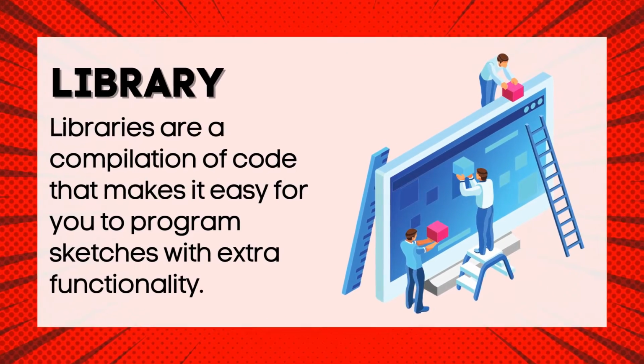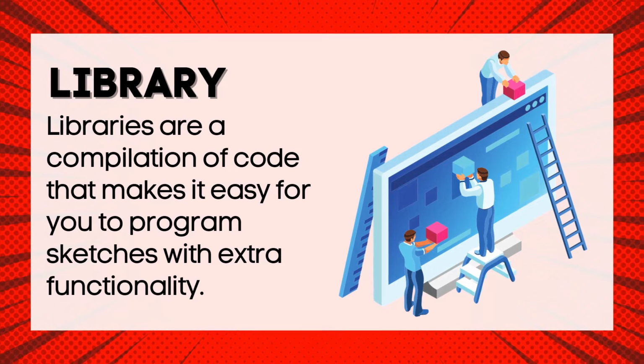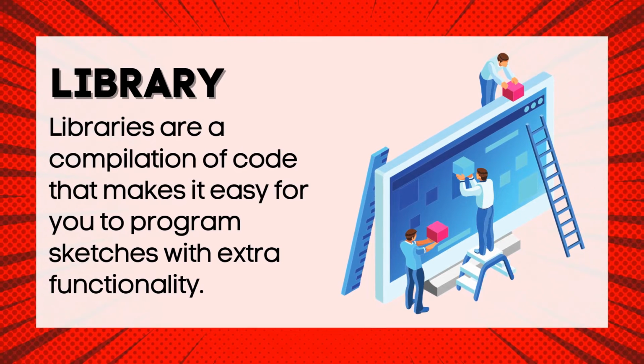Library. Libraries are compilations of code that make it easy for you to program sketches with extra functionality. Files included in a library are written in C programming. To use a built-in library in a sketch, simply go to the Sketch menu, choose Import Library, and select from the libraries available. To install a new library into your Arduino IDE, you can use the Library Manager, available from IDE version 1.6.2 and up, or you can install it by dragging the downloaded library to the library folder of your Arduino IDE.